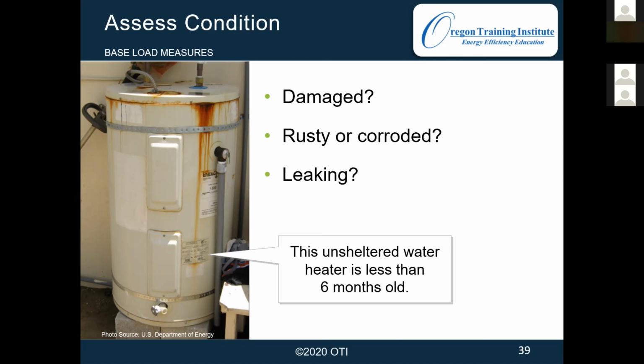But the pressure relief valve is going to prevent that from happening. So if something happened, it shorted, and it was overheating, that pressure is going to be coming out of that. And it needs to be piped somewhere safe where it's not going to be a burn hazard, shoot off at somebody, or also damage the building.